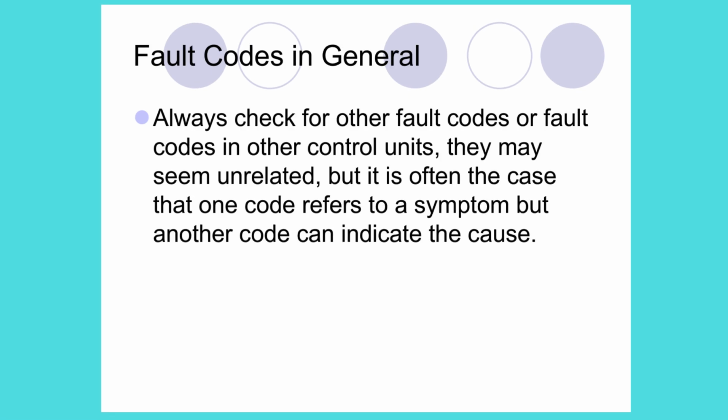Always check for other fault codes or fault codes in other control units. They may seem unrelated, but it's often the case that one code refers to a symptom, but another code can indicate the cause.